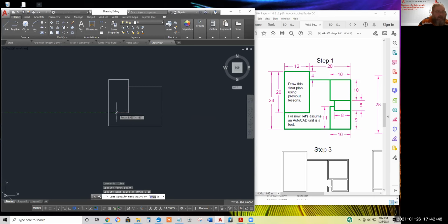And fortunately we got an O snap there, but the intersection O snap would work if we didn't have a break there. Enter, enter. I'll start here and come down 10. We're getting something. Our mission is to convert these into double lines for the widths of the wall.